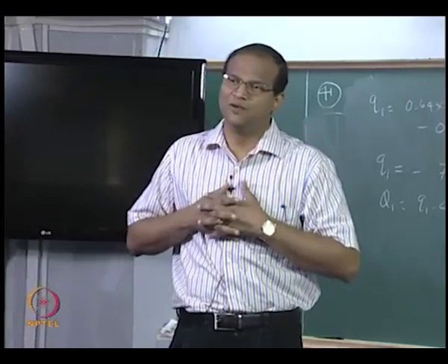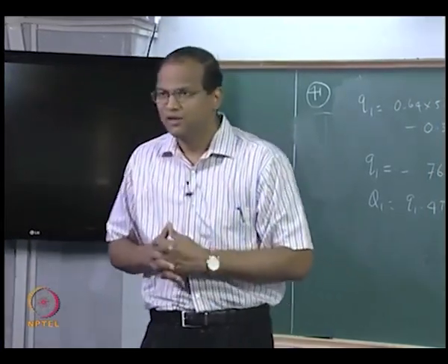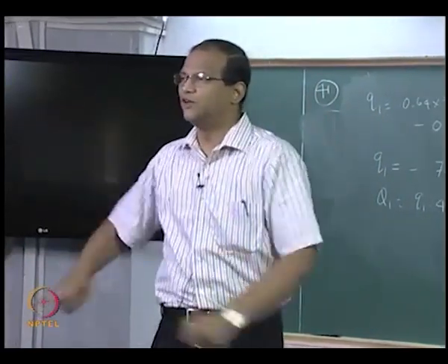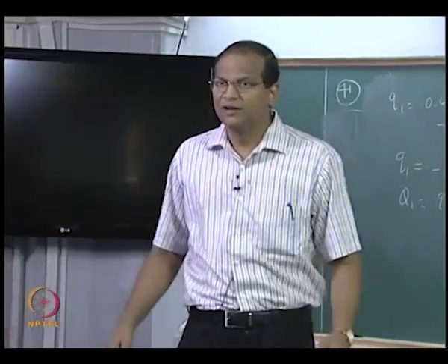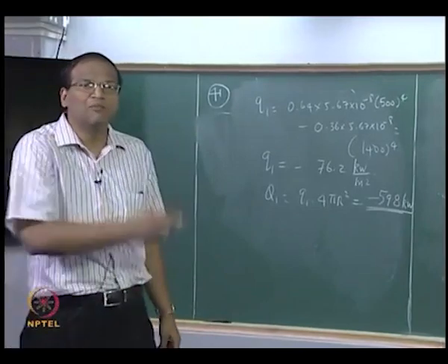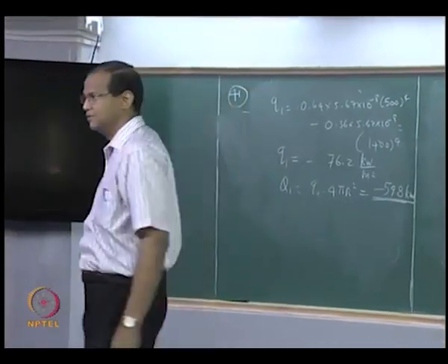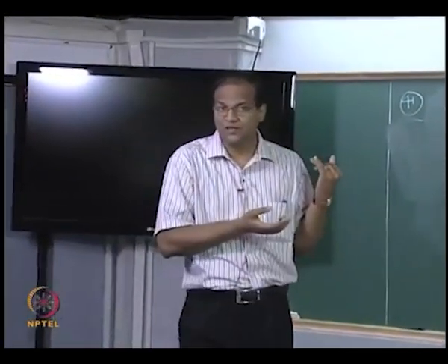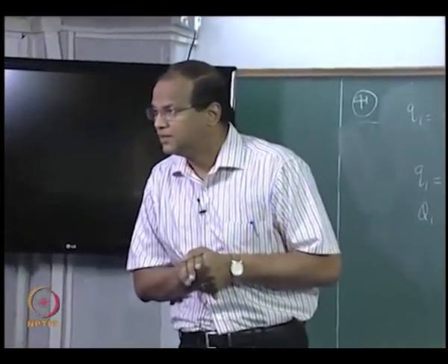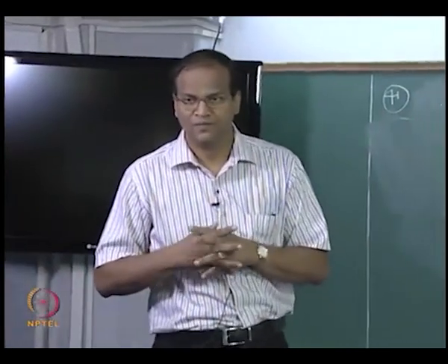allow it to reach a temperature of 1500 Kelvin, okay, and you get a mixture of CO2, H2O and N2. It is possible to put tubes on the outside of the spherical cavity, send water and heat water at the rate of 60 kilowatts. This is the radiative heat transfer power which the gas is capable of transferring to the wall. So as you can see, this will be very important in furnace calculations, design of radiant superheaters and stuff like that. So it has got engineering applications.